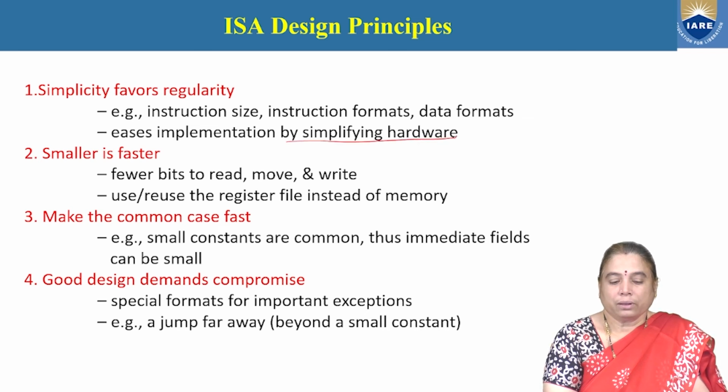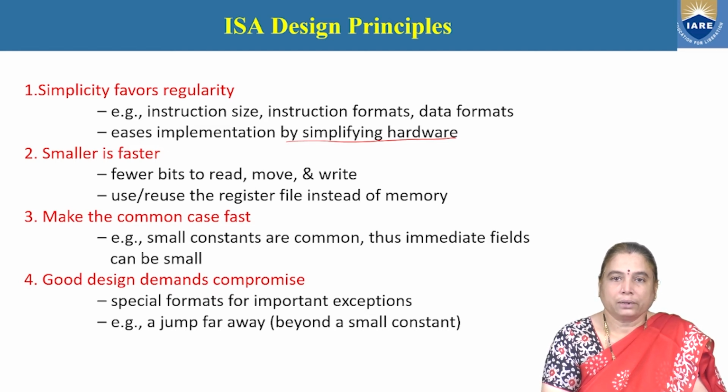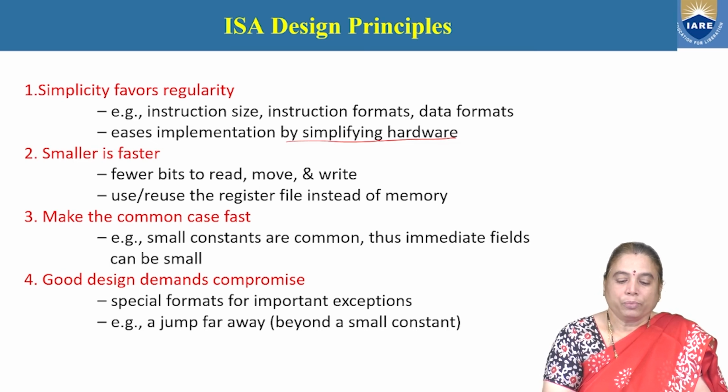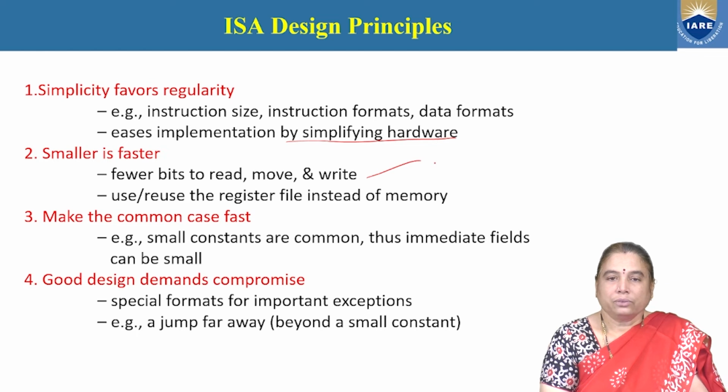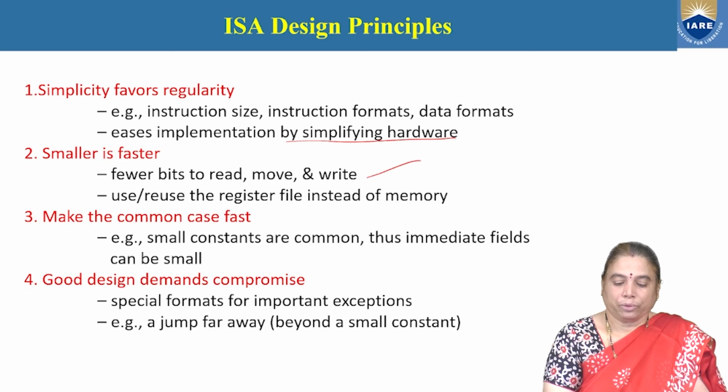So, simplicity has to be considered during design of the instruction size, instruction format and the data format. Smaller is faster. Few bits to read, move and write. So that the instruction execution takes less number of cycles in order to execute.